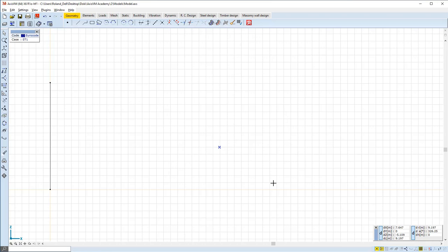If coordinates are given manually instead of graphically, like we just did before, there are some things to consider. The first one is the difference between relative and global coordinate input. By default, relative coordinate input is enabled. That means inputs are measured from the insertion point, blue crossed on the screen, which place can be modified with the Insert button, but it always moves automatically to the last action point.